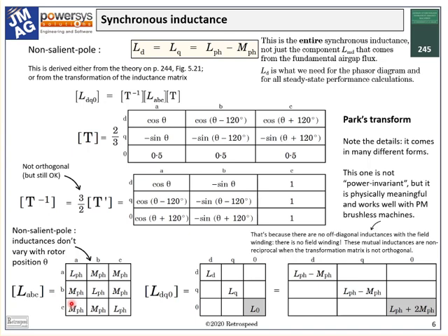This is very nearly the case in the surface magnet motor, and it's what we mean when we say that it is a non-salient pole machine. In the IPM, these inductances vary with rotor position and also with current, and the situation is a lot more complicated. We call the IPM a salient pole machine because its inductances depend on rotor position.